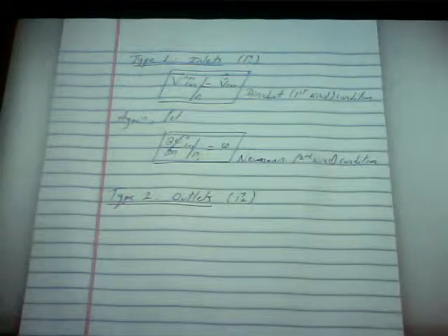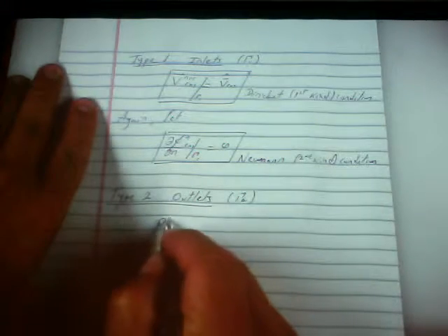An outlet is an open boundary that we decide to cut at a point and say from this point on we don't care about what happens to the fluid. But the fluid still exists past the boundary, right? It has to go somewhere. We're just saying at this point we don't need to know anything about it. So we need to be careful about how we set that up. Normally, what we know at the boundary is the pressure.